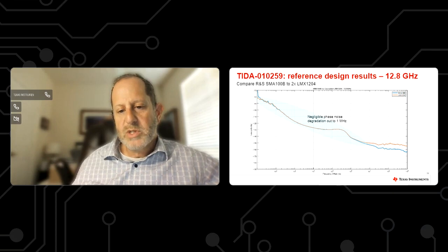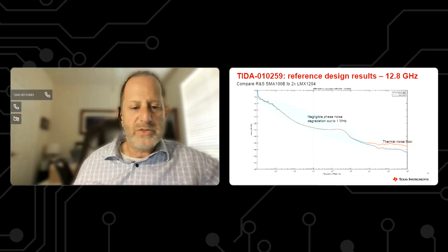And then if we look past that, we do see some thermal noise impact, but it's pretty minimal out here. So we can cascade up 2 layers, 3 layers, 4 layers, depending on how many clock sources your phased array system ultimately needs.